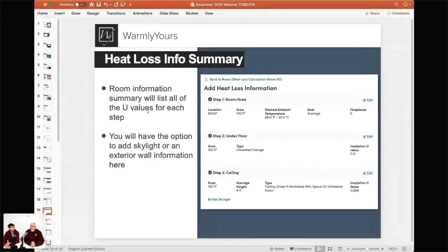Yeah, and that's definitely the number one question that we're getting, about doing the heat loss, and that's what I'm also recommending most of the time: do the heat loss calculation or supply us the information about each room that we're trying to heat here. So we're going to be doing that room by room, because in the very end of the whole process, the benefit of using floor heat as a primary heat source is that you're actually maintaining a perfect climate in each room individually at any specific time and day. So that's a very great part of it.